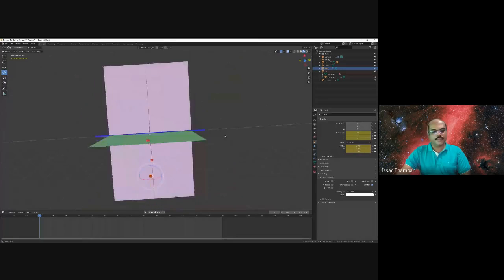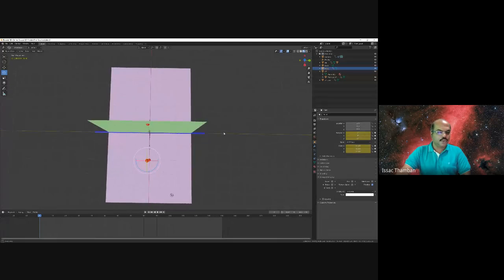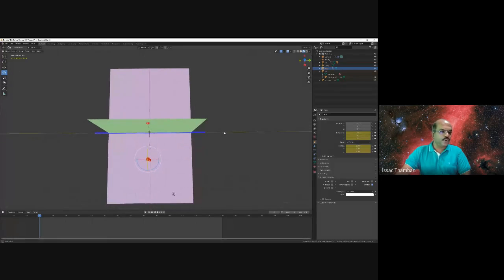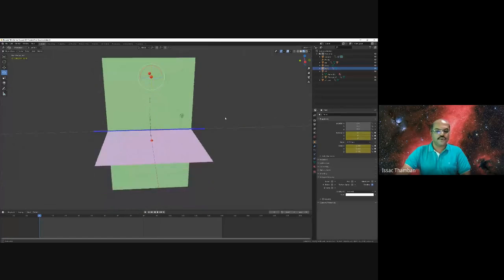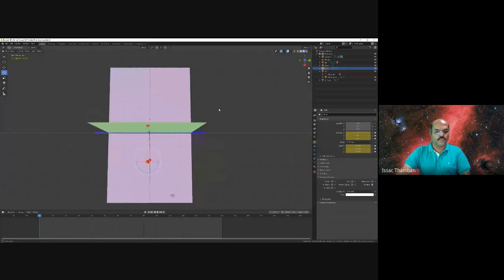And this projection is the top view. This is the front view, and this is the top view. This front view is also known as the elevation. Elevation is the engineering term. And for this top view, we will use another term called the plan.